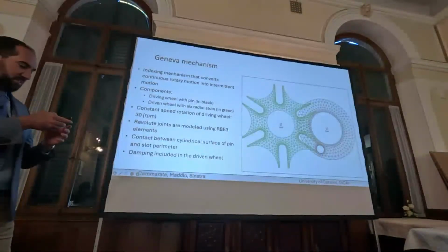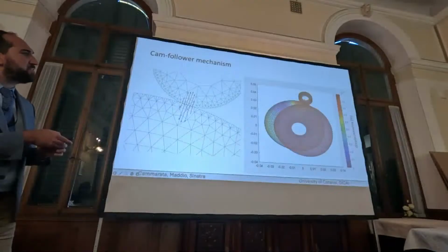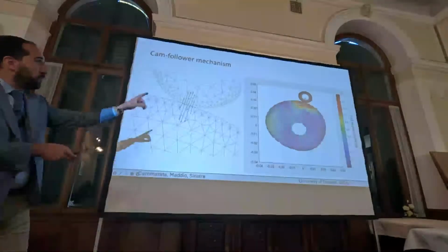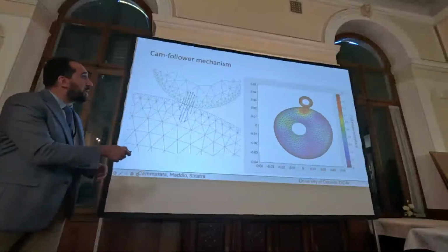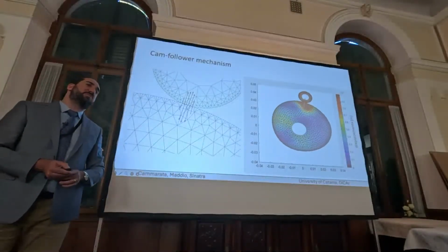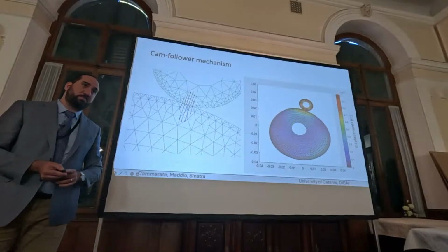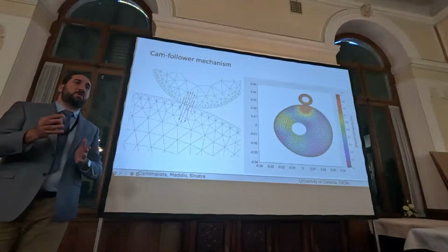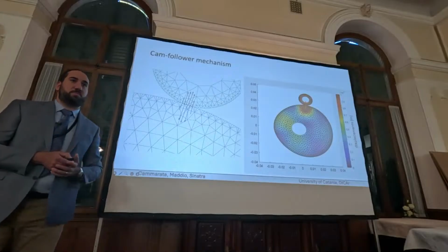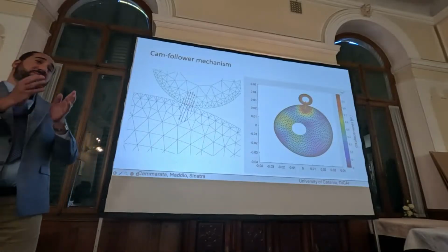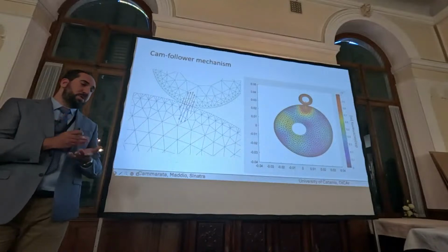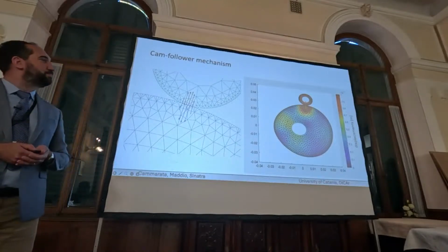In this case, for example, I remember for the cam one, in order to capture the local deformation at this point, we use the first 20 natural modes. If you increase, like going from 20 to 50, results don't change anymore. But this changes from case to case, so you have to check. Thanks.